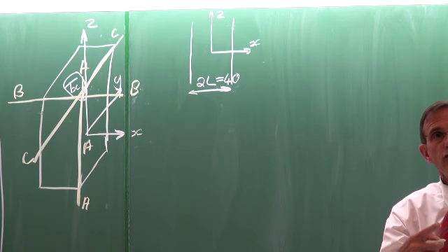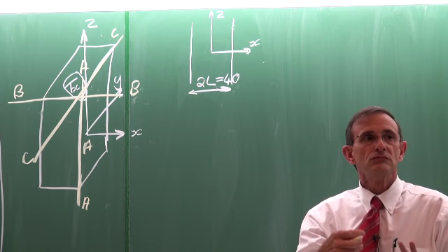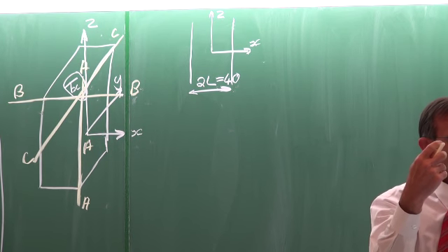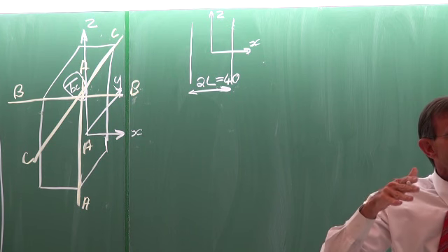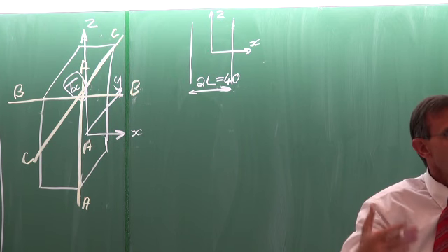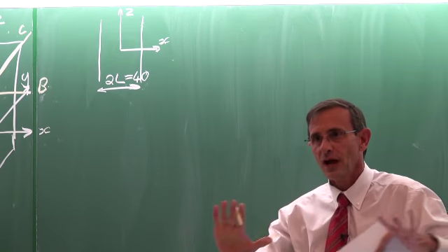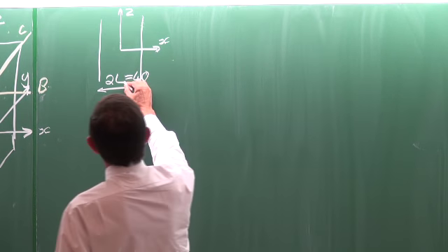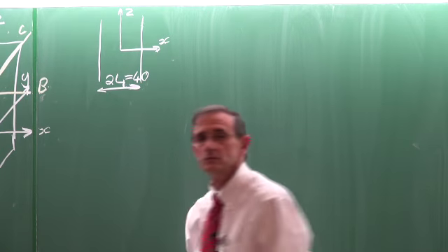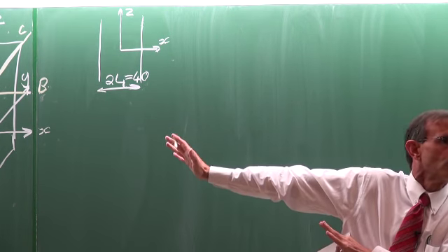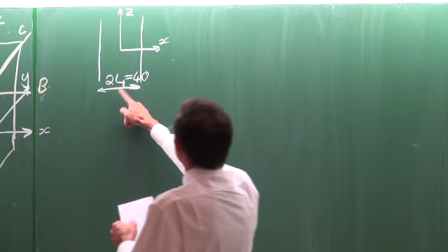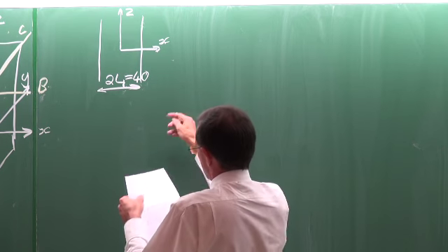And what we have to be careful for is that we now have 3 L's. And you're going to see later on 3 Biot numbers, 3 lambdas, etc. So you have to be very, very careful in your handling of it. So I'm going to call this L1, the first part of the problem. So this is 2L1, which is 40.